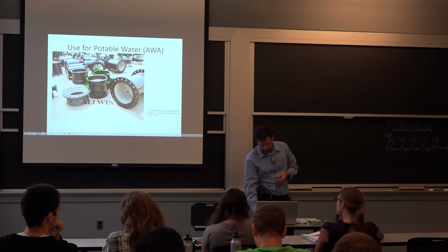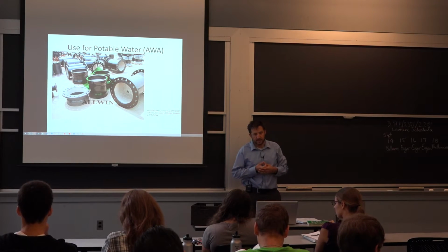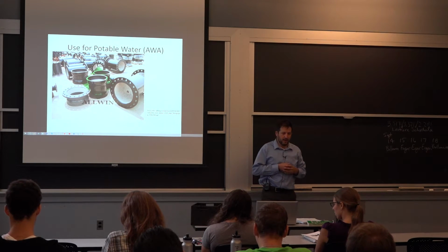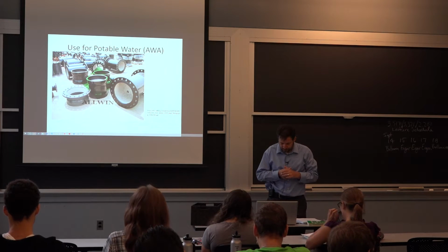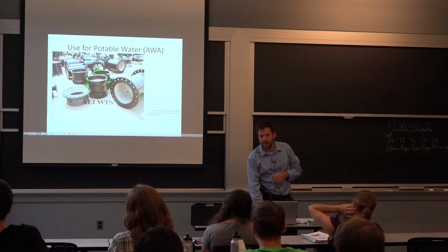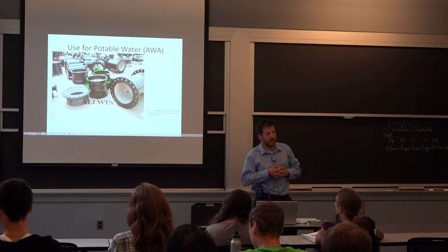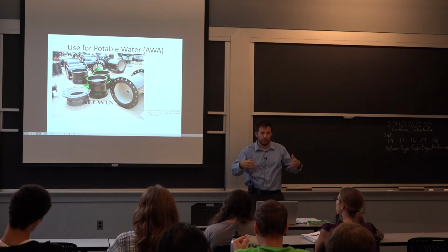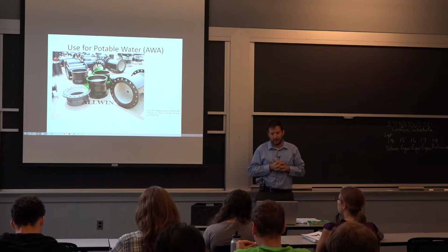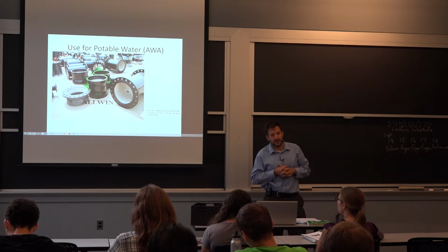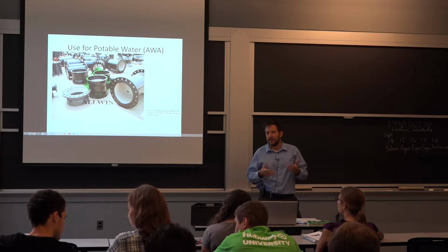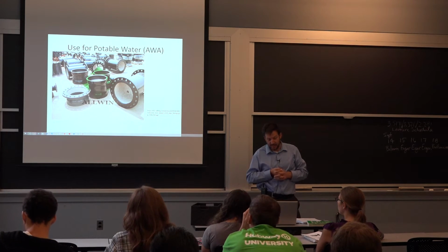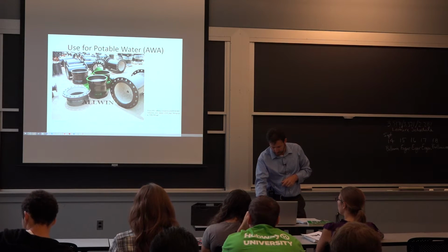So these are examples of large diameter pipes, and if you go to any plant and you see something this big, a lot of times it was cast. It allows you to do the flanges at the same time as the body of the pipe. So this is very suitable if you're trying to connect multiple components together. You do need a flange to put the bolts on. In volume, it's a very large industry. It's not something that's used a lot in advanced manufacturing, but if you need something big, these are the types of options that you're looking for.